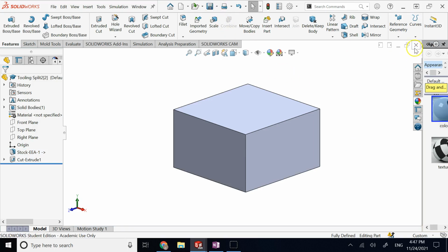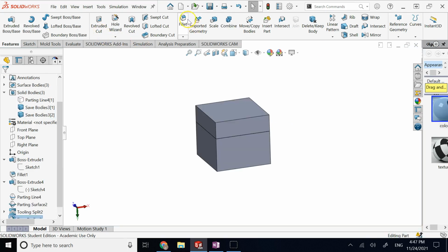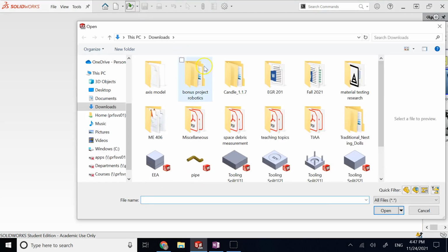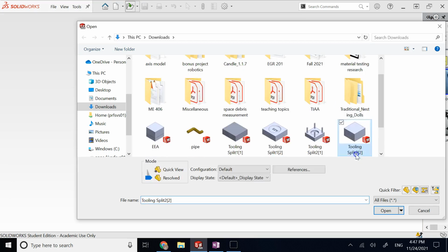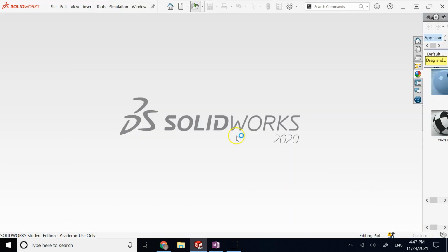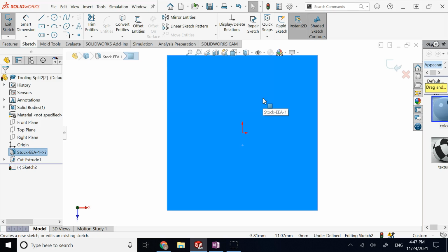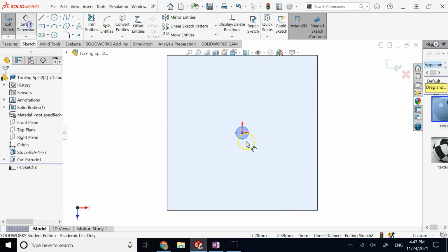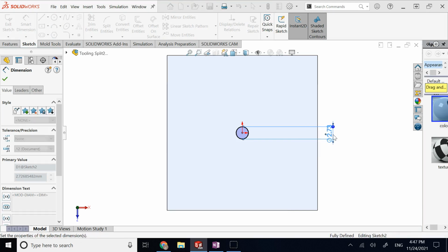And now that this is ready and the other one is ready, if you want, I can show you in an assembly, right? That's what my mold is gonna look like. One other thing that I forgot to do is, in the top part, I forgot to add the nozzle, because you have to have a way to bring in the plastic, right? So I go here, and then I create a nozzle. Now, of course, you want to make sure it is not super big. So maybe this, I make it like 2 mils.